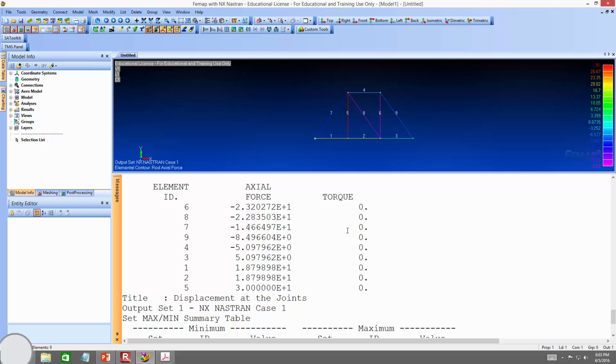And in addition, we got this triangular load. We need to address that. How can we apply that triangular load easily? Because if you look, there's no triangular load option, but there are ways that we can discretize and use load surfacing techniques and meshing techniques to represent that load. So, a couple different options for things we can do. Again, just more tricks of the trade for you all to be able to do these analyses.